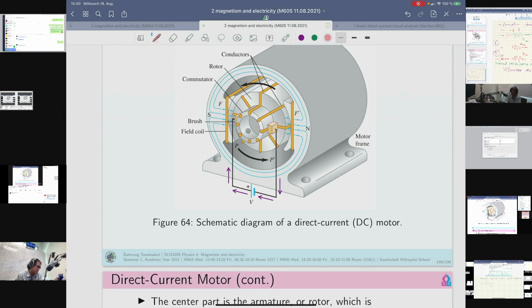you would get the torque induced from this one. And when this one moves, another pair is going to come, and it will let the current flow again through that pair, and there is induced torque. And you may ask me, what is the reason why we have several pairs of conductors?